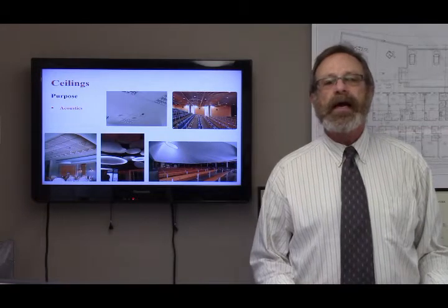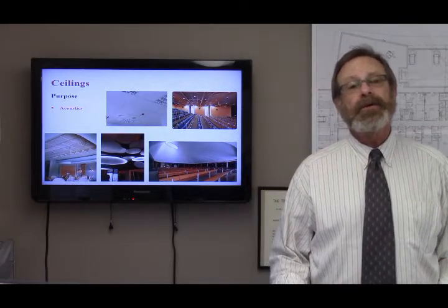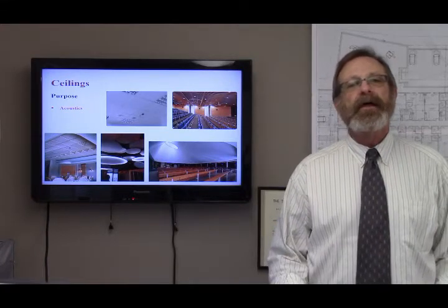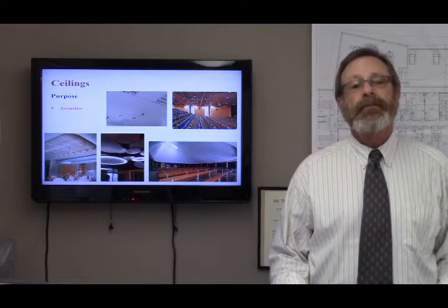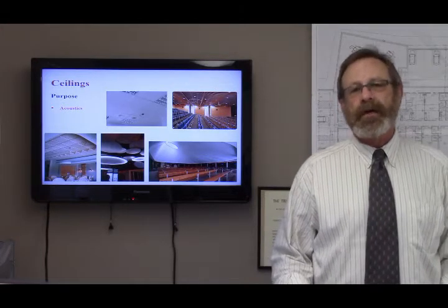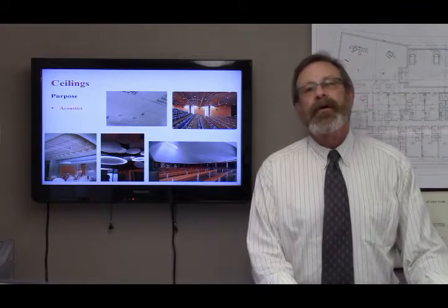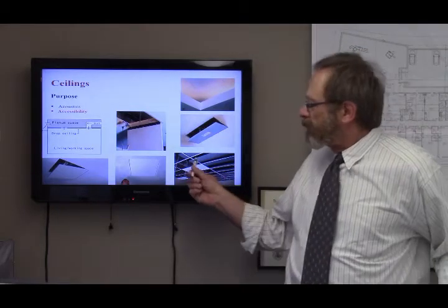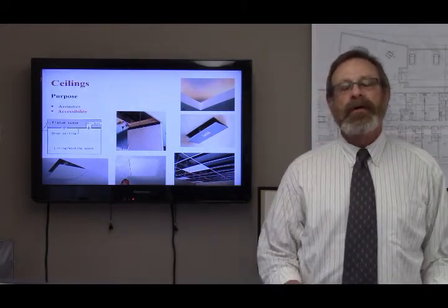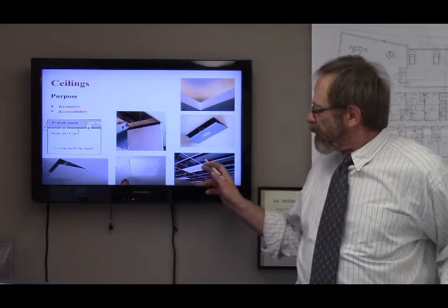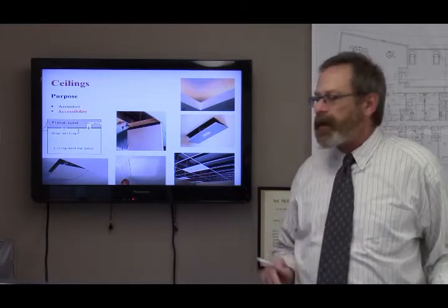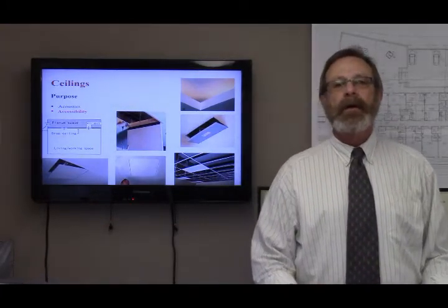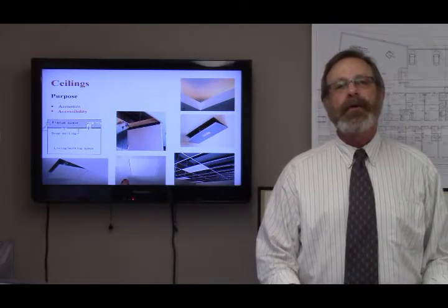Good acoustical ceiling tiles have a very high noise reduction coefficient, NRC, meaning that they absorb the majority of the sound that reaches them, while gypsum and plaster, by contrast, have a very low noise reduction coefficient, meaning sound reflects off of those materials. The space between the structure above and the ceiling suspended below is called the plenum. That area between the deck above and the drop ceiling below provides a zone for ductwork, piping, conduit, and other equipment.